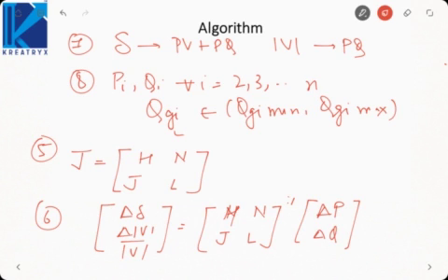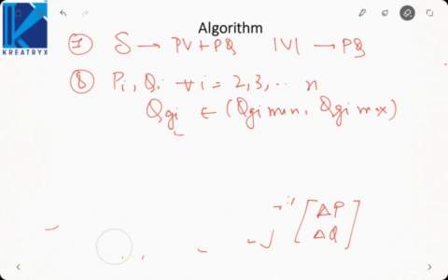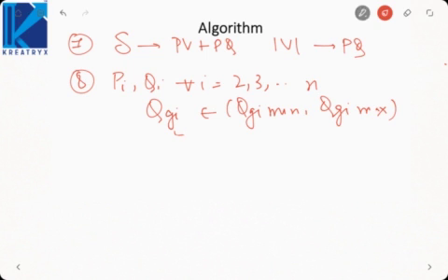Okay, and if it still lies in this limit, then the PV bus will be treated as a PV bus for the future steps. So then we will again calculate delta Pi, that is Pi supposed minus calculated. So we again get the mismatch vector.